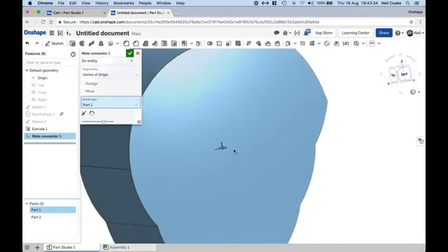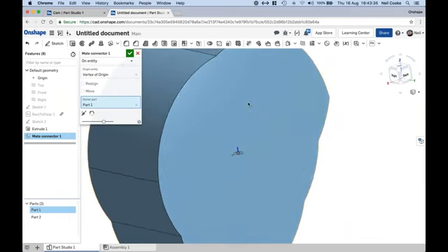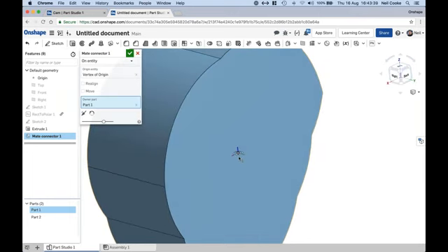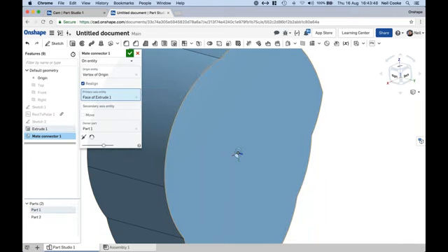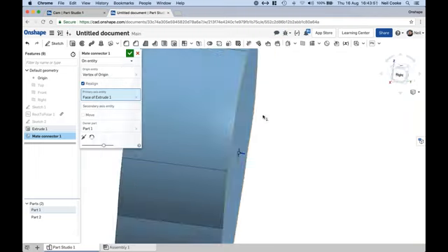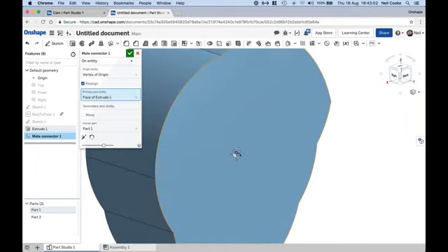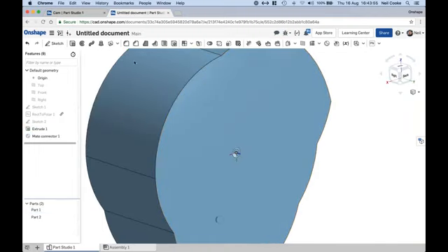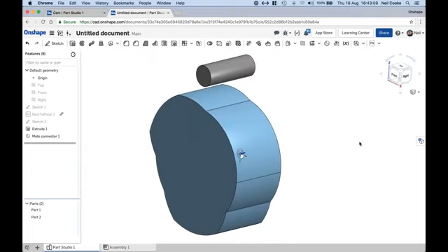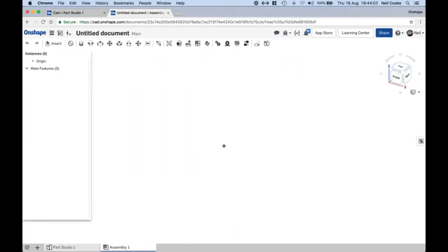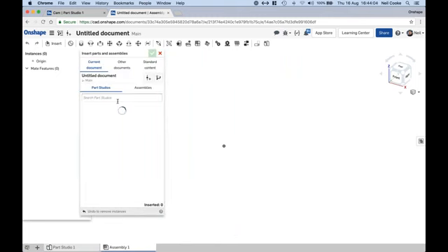That's going to be the owner part, which is the cam. The only other thing is they want the blue axis to be the axis of rotation. So we can change this on the mate connector by using the realign option, and the primary axis, which is the Z axis, we can click that. Doesn't matter which way it's going, just so long as we've got the blue axis going along there. Okay, let's create an assembly from this. So first of all, let's just insert those two parts.